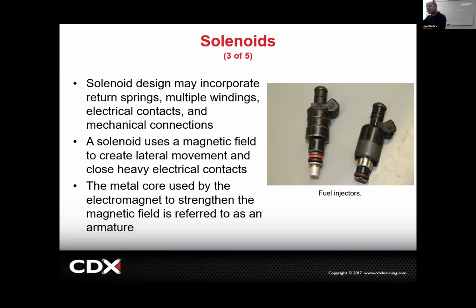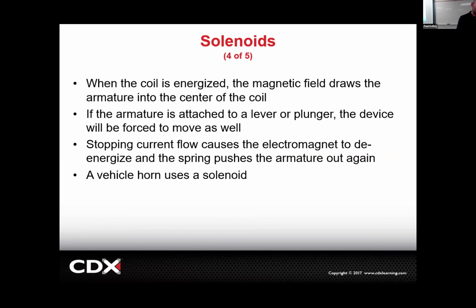If it doesn't tick, you'd be like, let me see if it's getting 12 volts and ground. If it's getting 12 volts and ground, it should move. But if it's not moving, then the winding, there's a problem in the injector. But if it's not getting 12 volts, you look at the diagram and you find out why isn't it getting 12 volts. Or if it's not getting ground, you look at the diagram and you measure and find out why it's not getting ground, right? And that's what we'll be doing for the whole rest of this semester, right?